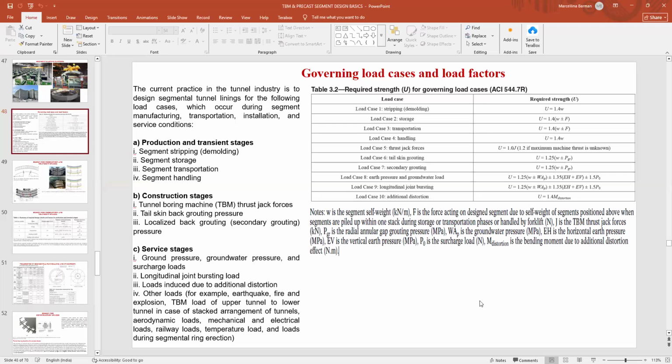First of all, exposure class, and accordingly, you have to determine what is your strength class, what is the minimum compressive strength, or what is the minimum cement content you will need to specify. That is the first of all. The software will come at a very later stage.